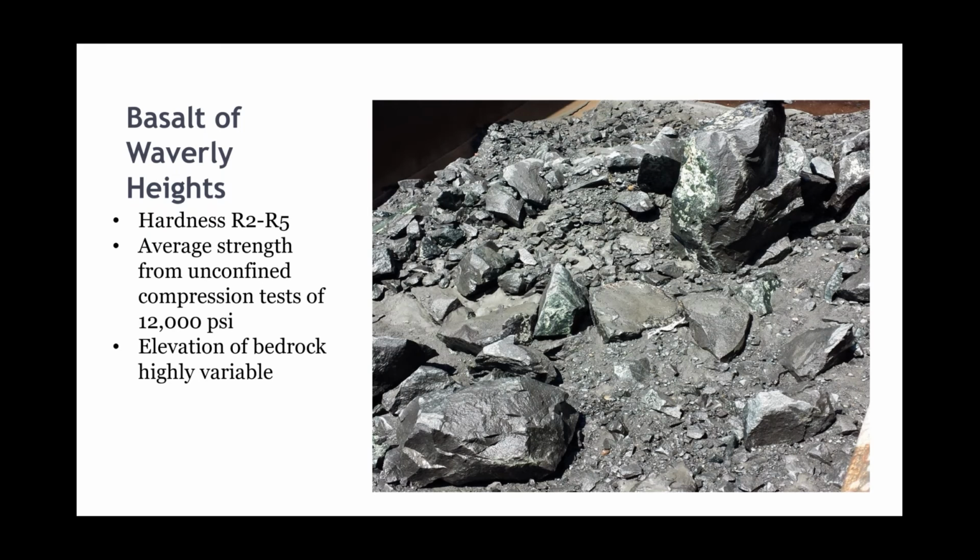No indications in the borings that there would be any solution cavities or voids or anything that would make us reluctant to rely on base resistance in this rock. That base resistance is there whether you're on the top of rock 20 feet or 50 feet into that rock. So as we all know, the area of a drilled shaft is a function of the diameter squared. So as we get to these big shafts, 10-foot diameter shafts, the contribution of base resistance is through the roof. It's a function squared. So if we can get them built right, and by that I mean cleaned and inspected and concrete placed properly, there is tremendous base resistance that can be realized in these large diameter shafts on rock of this quality.